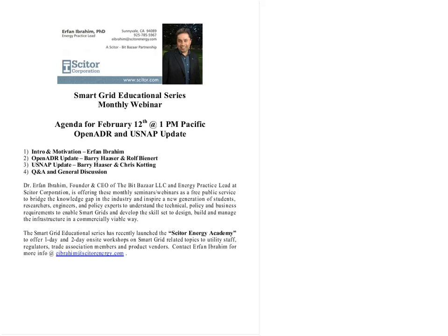Very good. Next question is, Dave Erickson asks, current DR systems I'm familiar with use an RF signal to do direct load control. Utility provides the RF signal. How would this be best replaced by an OpenADR USNAP solution? I don't think it needs to be replaced. It can work because the module will have the RF antenna on it, right? Yeah, the USNAP module will provide the receiving end of the RF communication. That's correct. Okay. So next question is Dale Gutierrez asks, is a possible migration a different band like the now functioning 60 gigahertz band or 802.11ad under review?